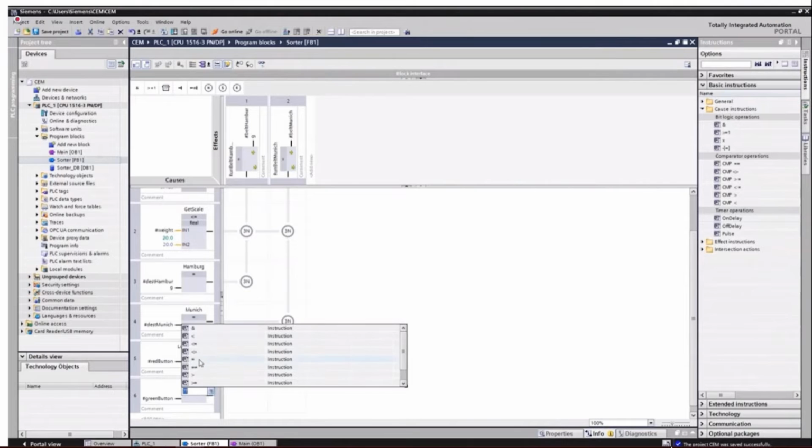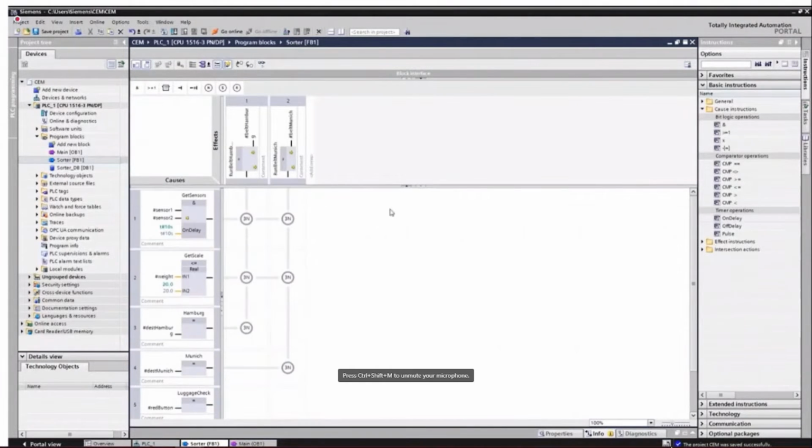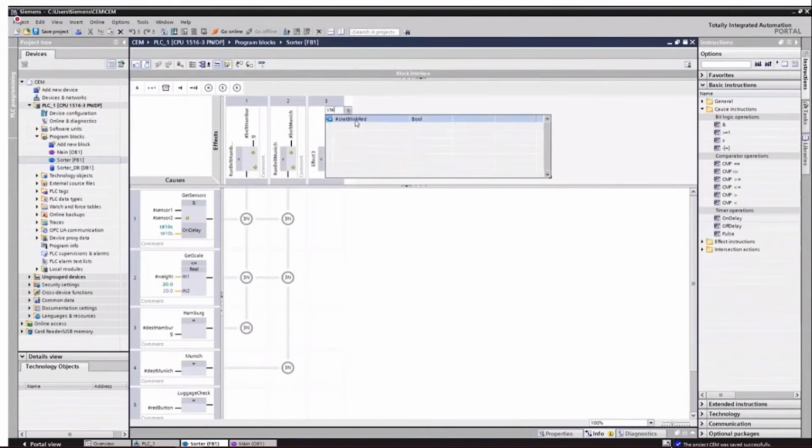Another part is basically to reset this, because once the checking is done, then again the conveyor should be in the running option. And for this we will select two indicators. One indicator will be a constant red, basically the stopping output, and another is basically the red blinking. So I can add another input to this particular effect part. To add, we just have to click on that output C, and we can again add it. So this is basically the output for the blinking part.